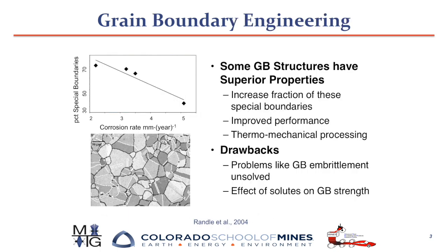materials. This nicely segues into the next concept that I would like to introduce, which is grain boundary engineering. Grain boundary engineering as a concept was introduced a few decades ago, and this stemmed from the realization by various experimentalists that some grain boundary structures, as highlighted in the micrograph, have superior properties than some others, and it is imperative to increase the fraction of these special boundaries to result in improved performance of the material.